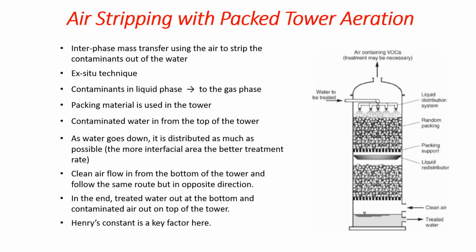For this assignment I picked air stripping with packed tower aeration method since it's one of the widely used methods in water remediation after extracting the groundwater from aquifer, which makes this technique ex situ. This technology is a physical process which transfers the contaminants in the aqueous phase to the gas phase for the purification of groundwater and wastewater.